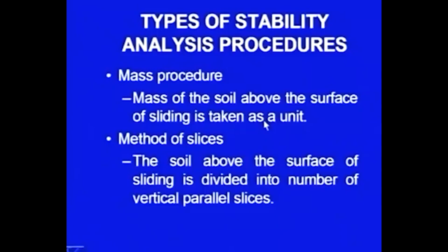As we discussed earlier, we are using the limit equilibrium approach. We will be assuming a circular failure surface, and above that circular failure surface the entire mass will be treated as a free body. So, in this first procedure we are treating the entire mass as a whole, and by taking it as a whole then we will be doing the analysis.